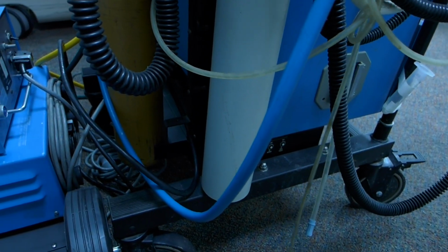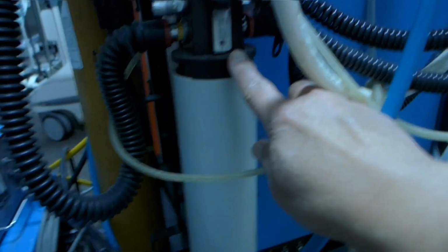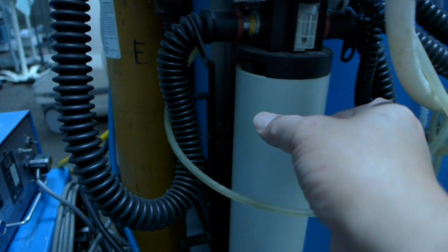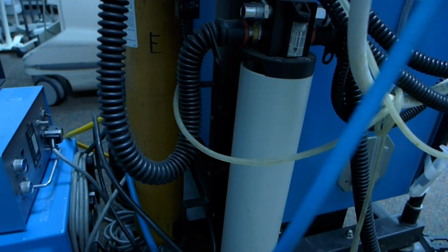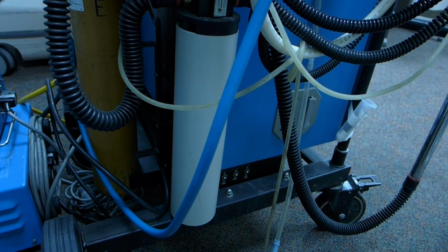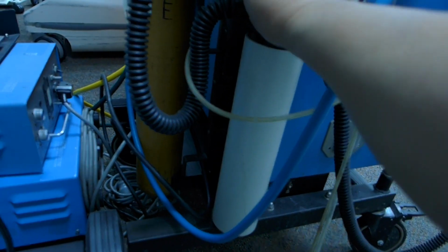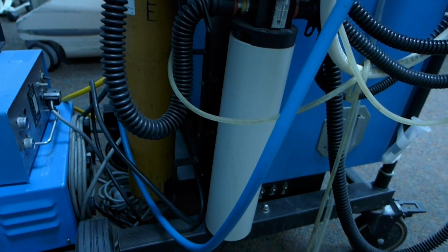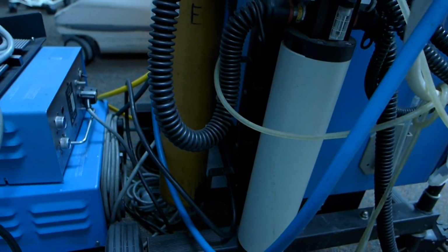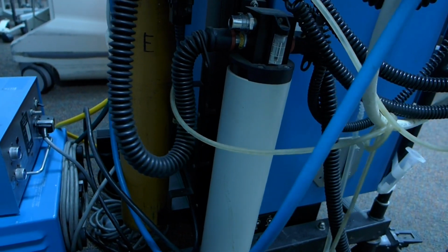So this one, not automatically, we have to manually set it to make sure the flow indicator floats in between. Basically, you can't dump the waste anesthesia gas into the operating room. Otherwise, everyone's going to fall asleep. So we have this connected to a vacuum system to scavenge all the anesthesia gas out of that operating room. This white one here is connected to the suction regulator,